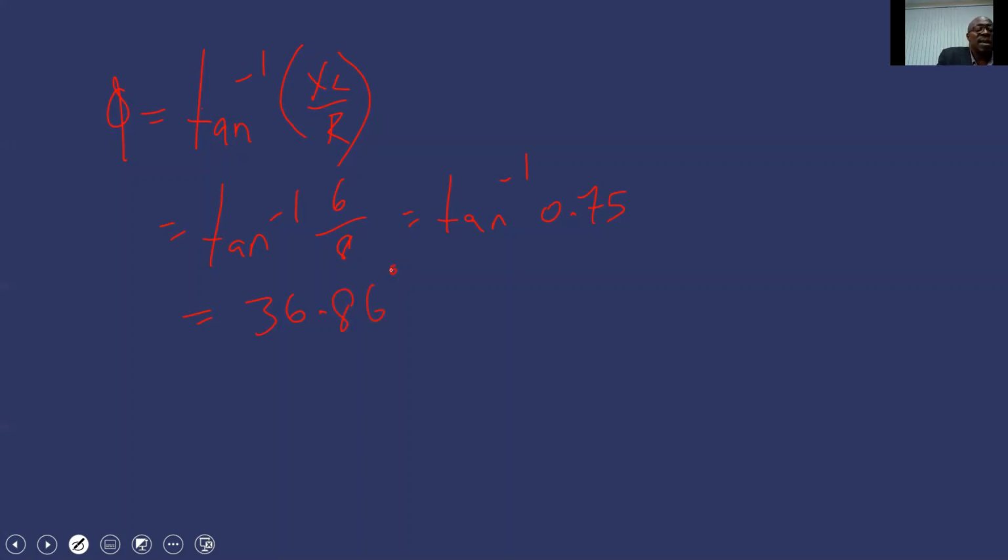So our current, I, is equal to 30 over 10, so the magnitude of our current gives us 3 amperes. However, we must indicate the phase angle. And we know, as we said earlier, that for the inductor, we see a voltage before we see a current. So the current would be lagging the voltage.